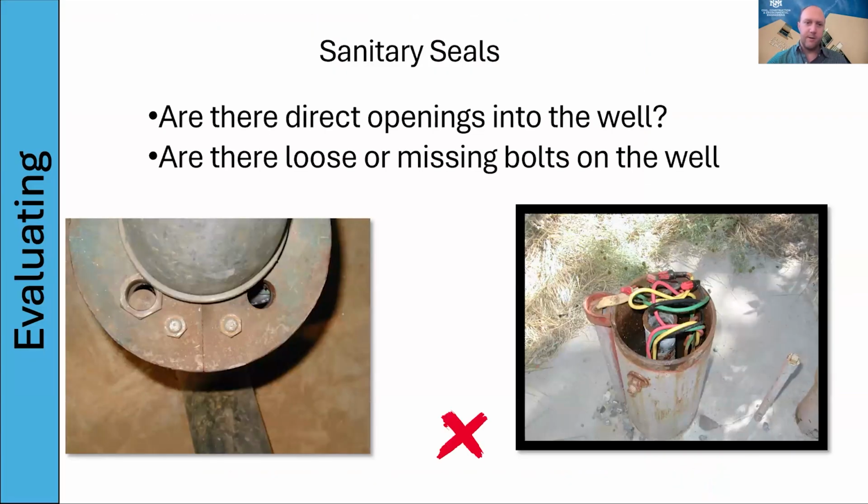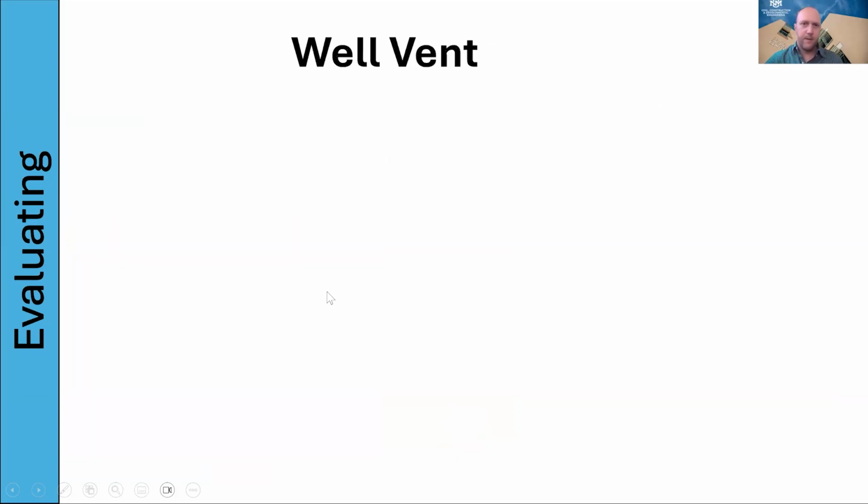Sanitary seals, make sure those are in place. There should be no openings into your wells. This one just doesn't even have a well cap at all. And this one has bolt holes, it looks like, that are not sealed up.